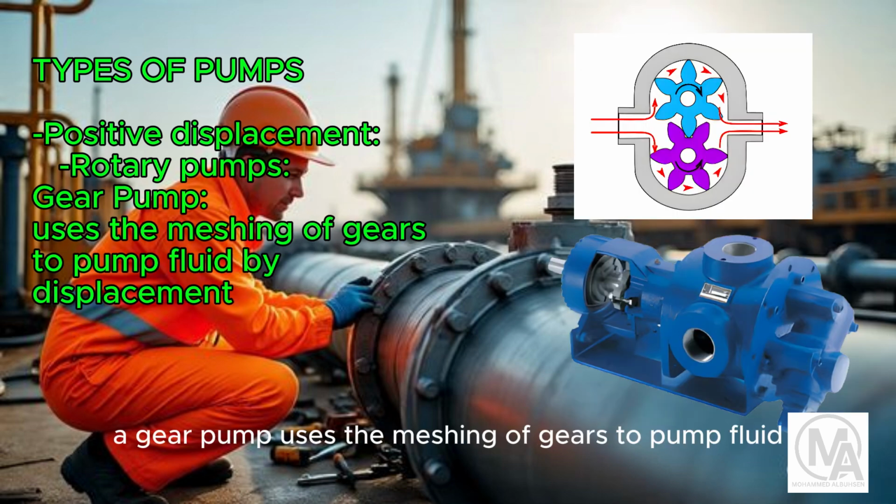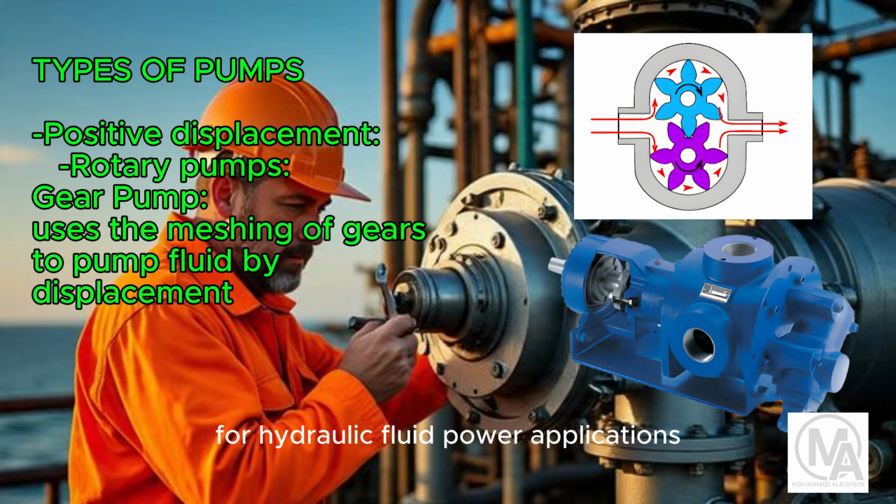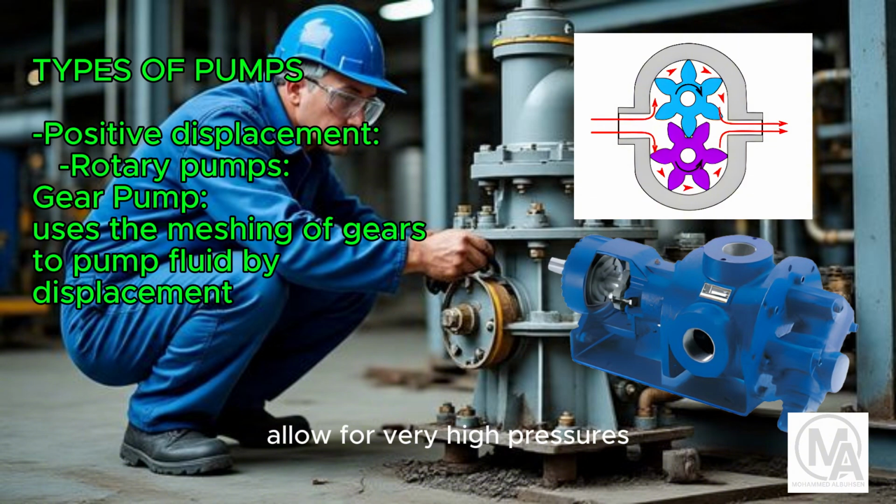Gear pumps. A gear pump uses the meshing of gears to pump fluid by displacement. They are one of the most common types of pumps for hydraulic fluid power applications. The rigid design of the gears and houses allow for very high pressures and the ability to pump highly viscous fluids.